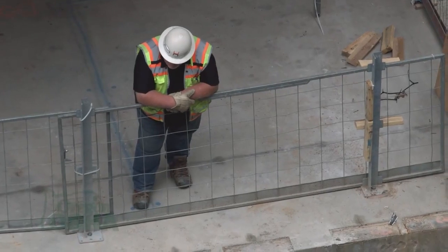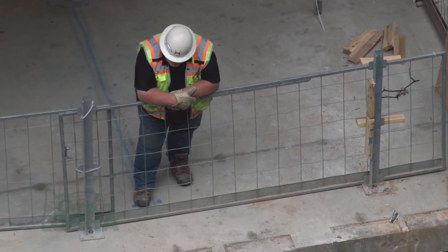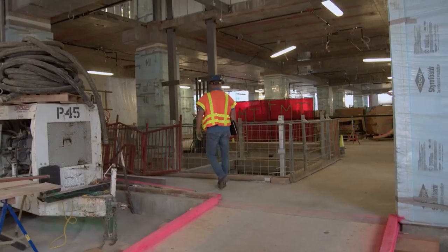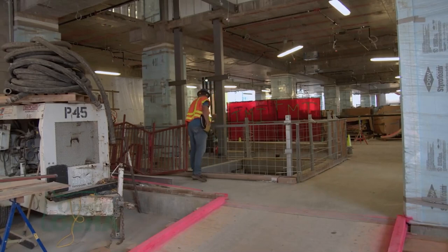As far as building guardrails and safety rails, it just depends on what the construction material is that you're having to work with. But building a wood rail, again, the bottom rail 21 inches up, the top rail at 42 inches, it's not terribly difficult. It does need to withstand the weight of someone leaning on that rail, so it does need to be positively fastened. It needs to withstand side pressure of 200 pounds, so it does actually need to be built correctly, but very simple to do. And there's also products available on the open market that you can buy that are an easy bolt together system that will do the same thing.